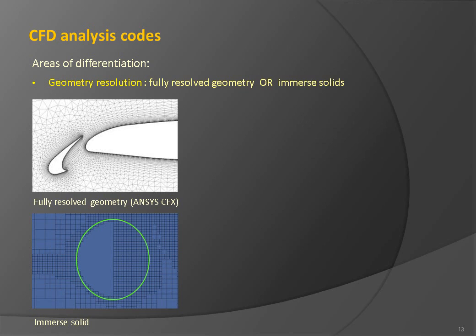The figure below illustrates the immersed solid method that simply blocks the flow in the cells where the solid body appears. In most cases, such a simulation domain crudely follows contours of the solid object, making the resolution of the boundary layer impossible.